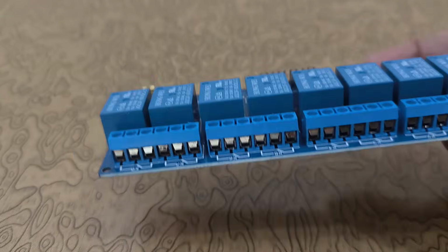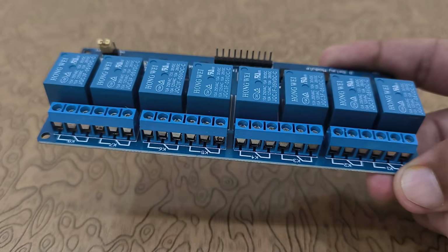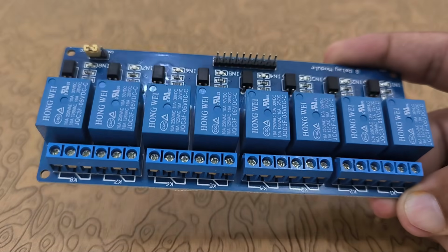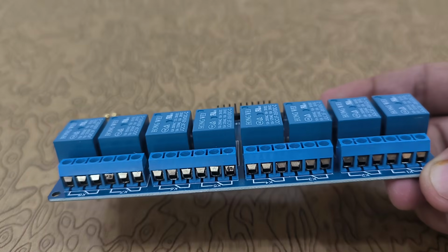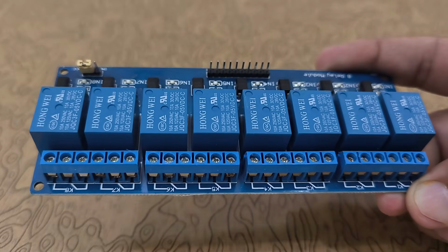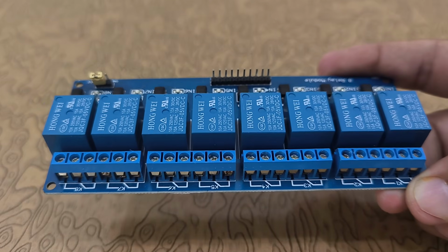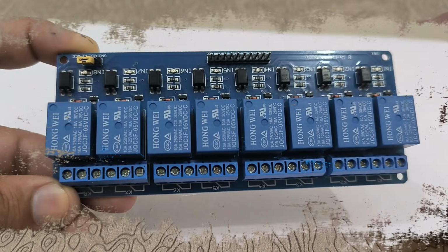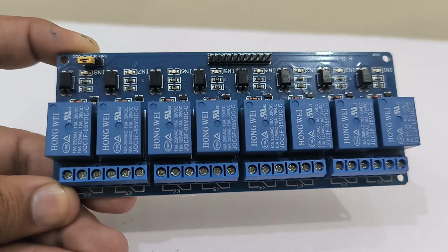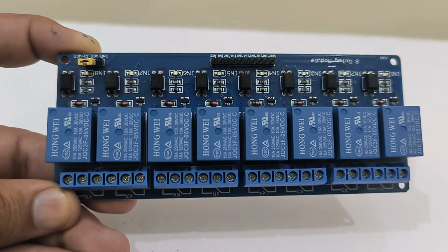On this side of the module, we have relay terminals. These terminals are used to connect our lights or other electrical appliances. Each relay provides 3 terminals: common, normally open, and normally closed. For most home automation projects, we will use the common and normally open terminals so that the appliance remains off by default and turns on only when the relay is activated.